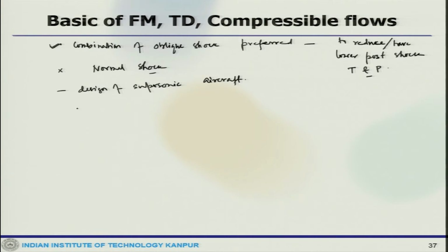But in the early days, supersonic jet engines were designed using compression through a single normal shock. When you use a single normal shock, there are limits of operation, because behind the shock the flow is immediately subsonic, which means a drastic change in properties.